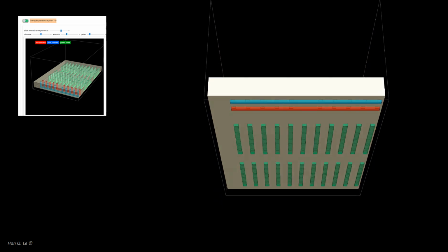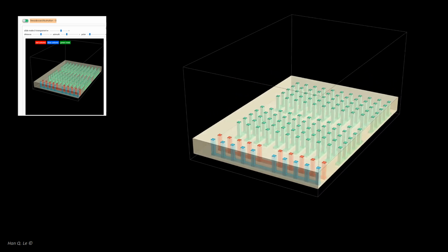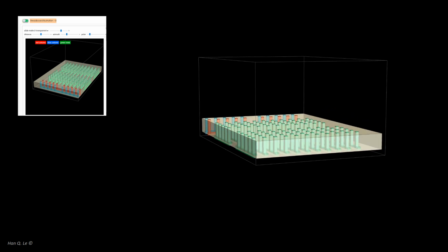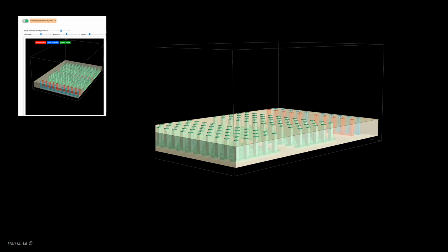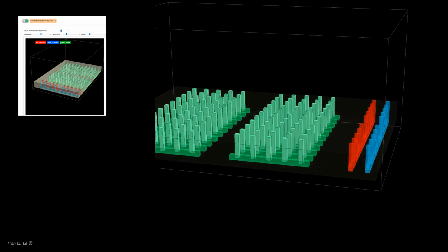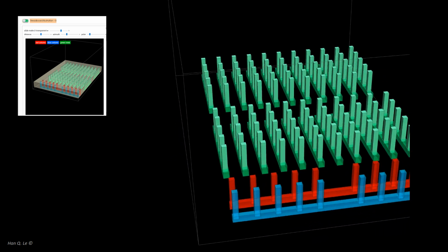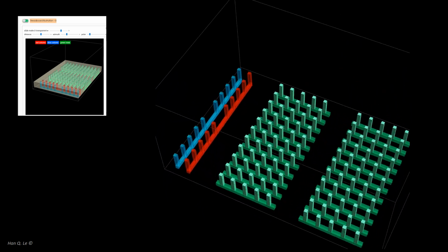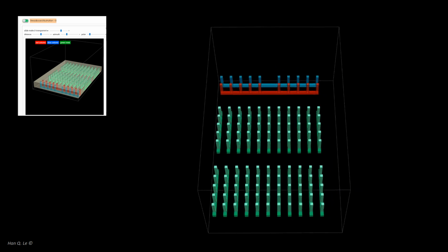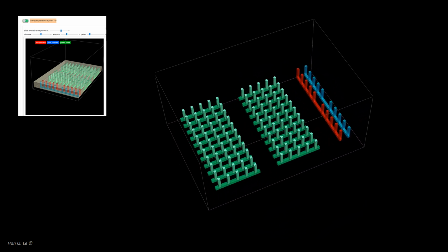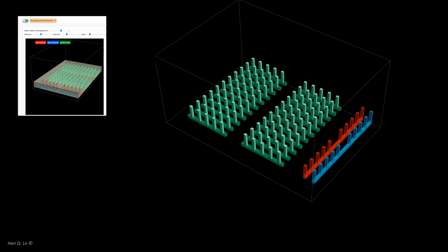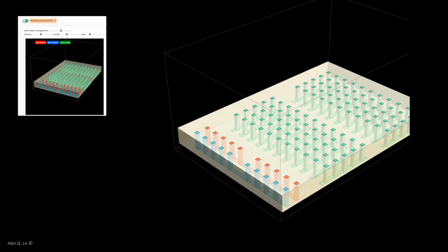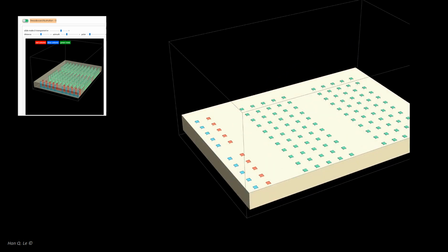While looking at the breadboard in your hands, envision in your mind what the electrical connections inside the breadboard would look like, if the cover could be made transparent. Move, tilt, and rotate the real breadboard in your hands, and use the applet for illustration. It takes only a short time to start getting an image in the mind, or a gut feeling, of how the breadboard works, and how to use its built-in electrical connectivity. Hence, one can use a breadboard without an excessive use of wires to connect the electrical devices. Of course, wires are still needed, but only in moderate number.